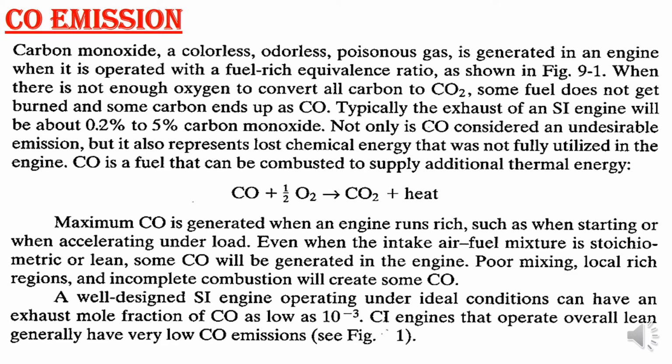Carbon monoxide emissions are high when the engine is at idle, and during deceleration it is also very high. They are lowest during acceleration, that is, when you reach a steady state of speed, then the formation of CO will be very less. Closing of the throttle valve reduces the oxygen supply to the engine, which is the main cause of CO production. So this is how CO is produced in the engine.